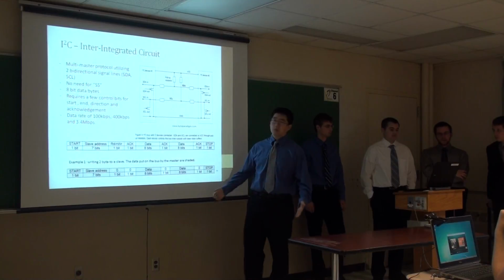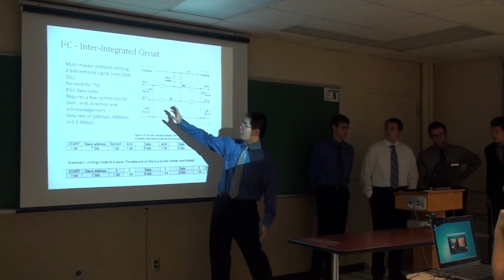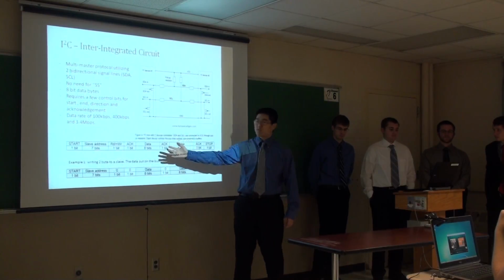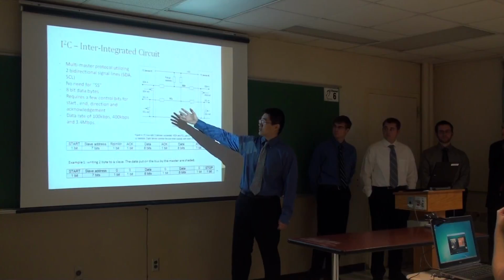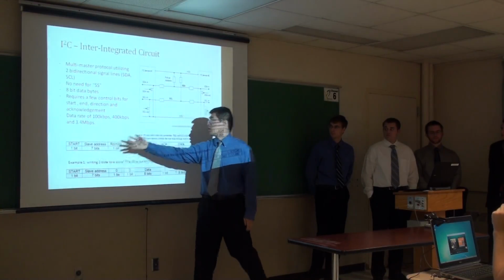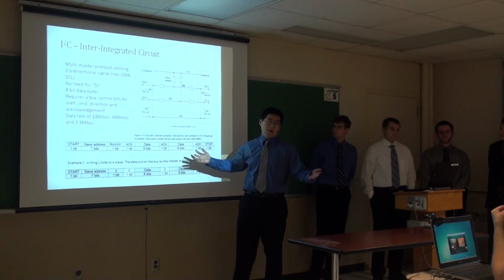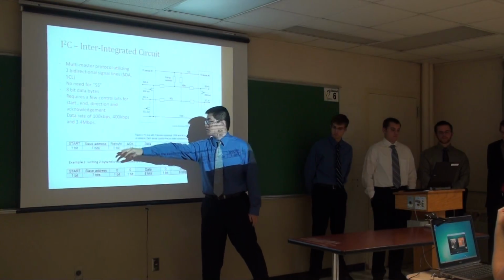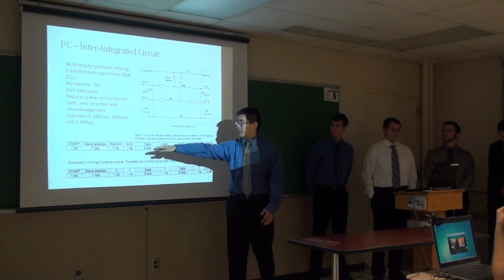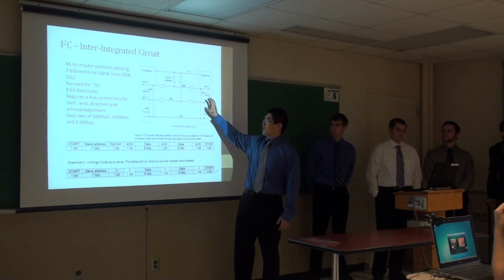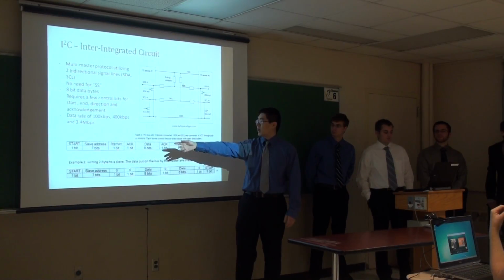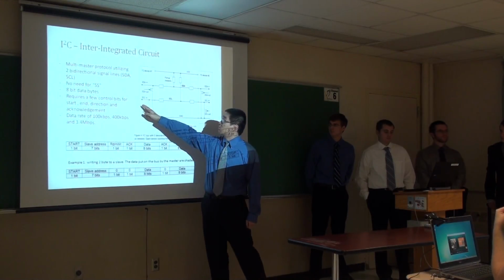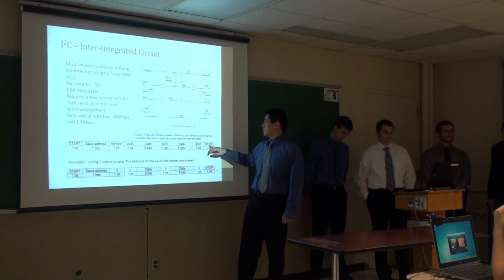So what happens is that when the master wants to communicate with the slave, the packet it sends has the address selected. For example, the master first starts with the start bit telling the accelerometer, hey, I'm about to send an address, so please pay attention. That start bit is followed by the 7-bit address and a read or write command, depending on what you want to do. The slave compares its own address to the address sent by the master, and if it is the same, it sends an acknowledge bit back to the master. If it's not the same, it just waits for the stop bit.